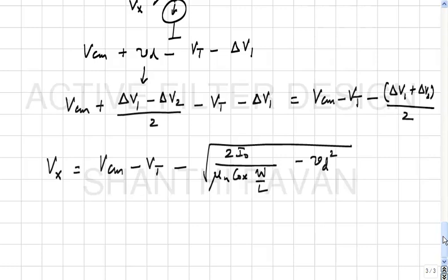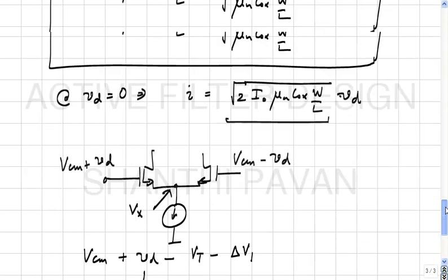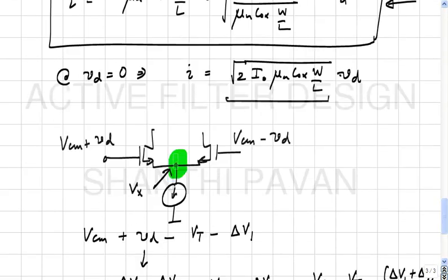To get something which is proportional to the square of the input differential voltage, which is needed in several applications, one often taps off the source coupled node. You understand? By exploiting the property of the differential pair, that this node, for large Vd, will have a potential which has got a square term, which means that it can be used to sense the square of the input differential voltage, and that's got some applications. You understand?